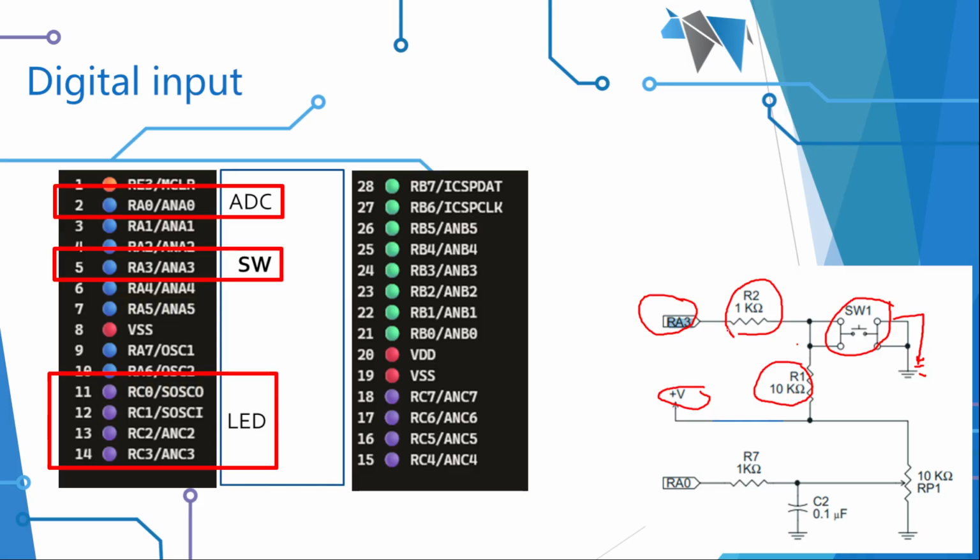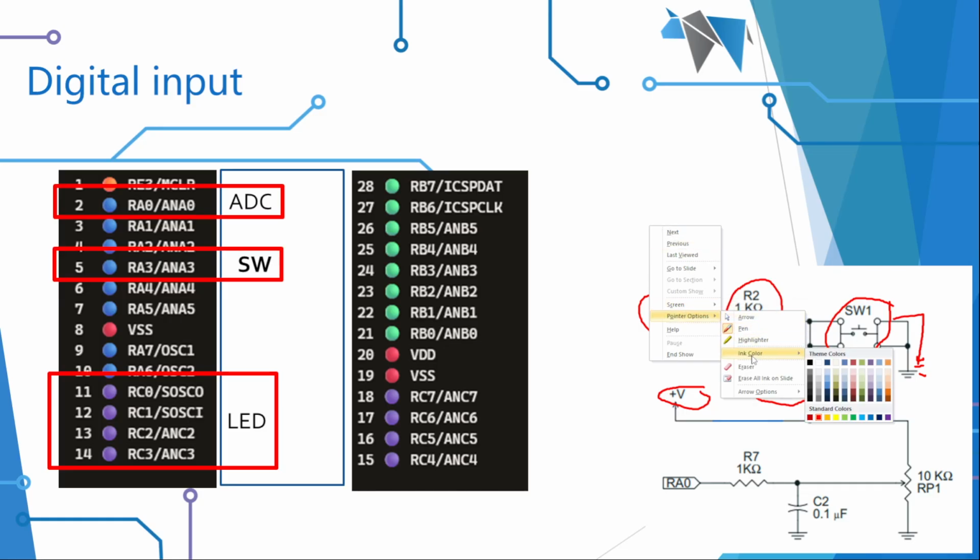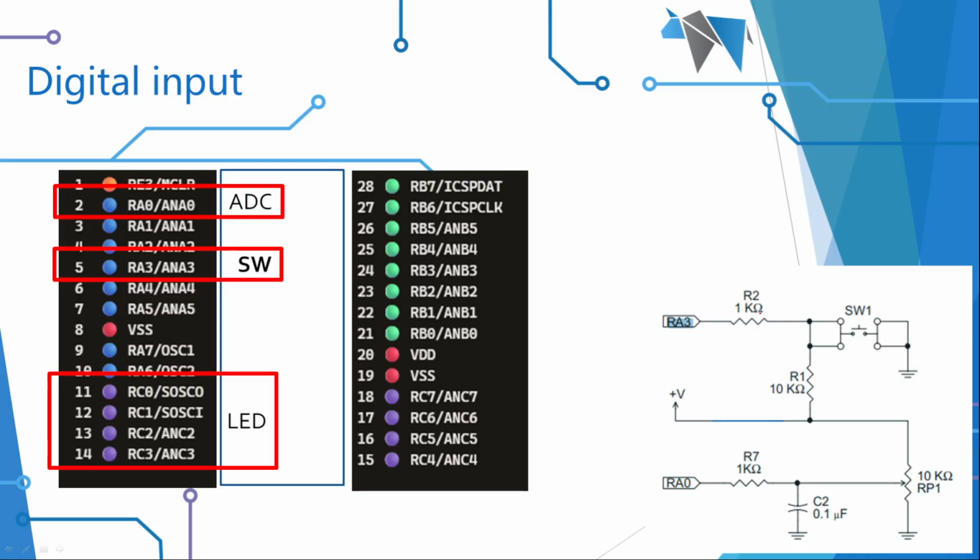This is good practice. This limits the current, and the current is going to come from the high voltage round here, and that's pulling it to 5 volts into the switch. That's what the protection is. So I've got it pulled up with a 10k and current limited with 1k, and that's really good.